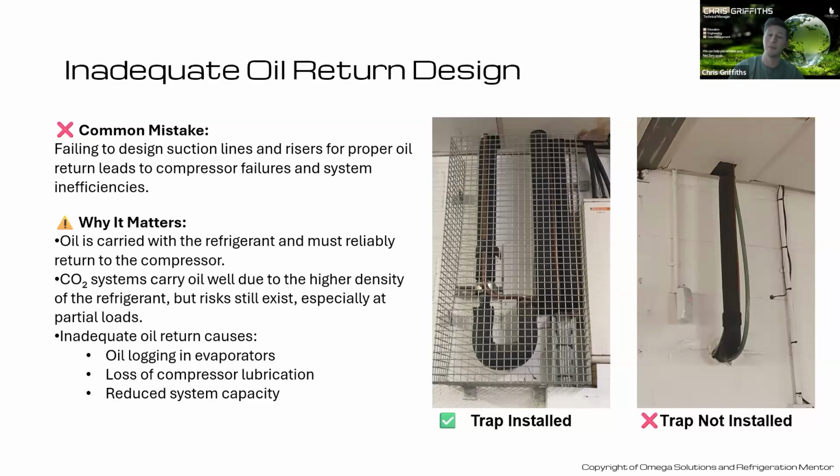It might be sized perfectly well to accommodate a full load, but when we get down to part load conditions, there's not going to be any velocity behind that to try and return that oil. So making sure it's actually designed effectively is important there.